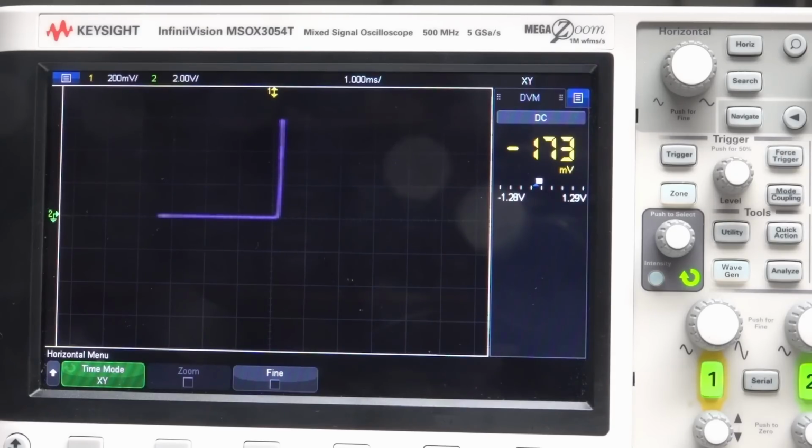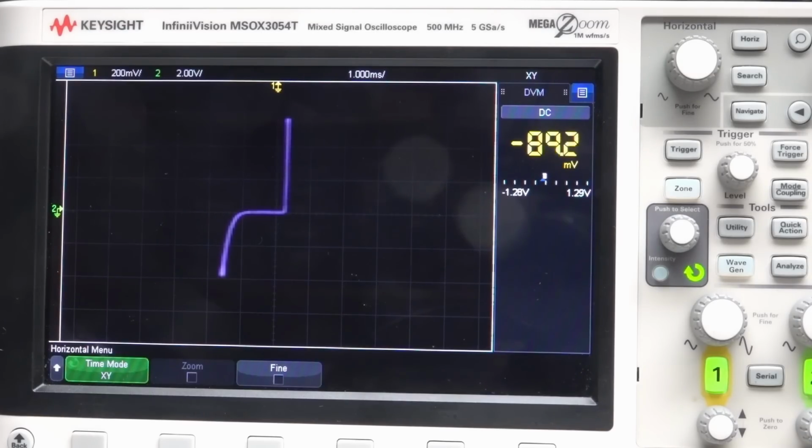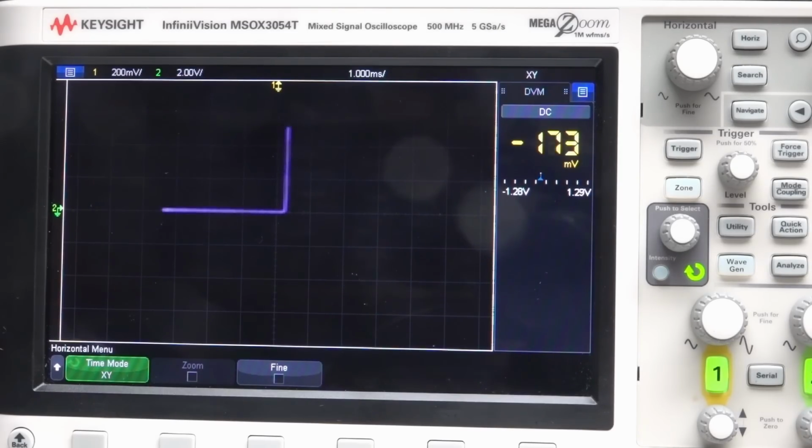Now what is this? This is a typical diode curve where the bend is at 0.6 or 0.7 volts. And what is this here? This is a Zener diode, which looks very similar on the positive side. And then there is a not so sharp bend at about minus 3.3 volts, because this is a 3.3 volt Zener diode. This is, by the way, a transistor between base and emitter. This looks like a diode, and it is a diode. And between base and collector is also a diode in the other way around. So you see, each part has its different curve, and we will use this now to do some analysis.